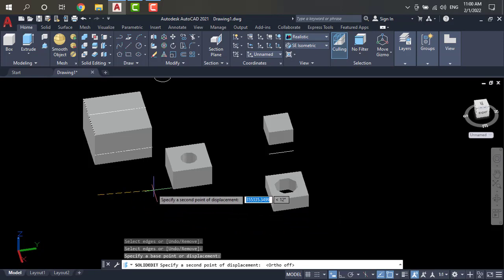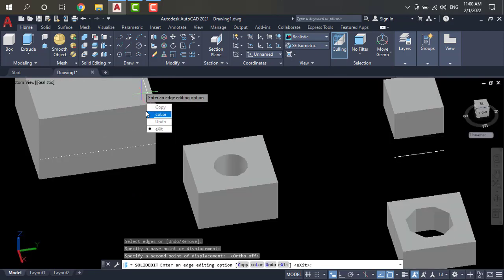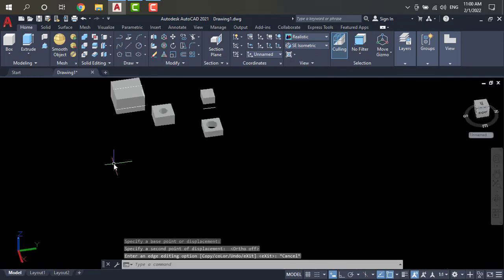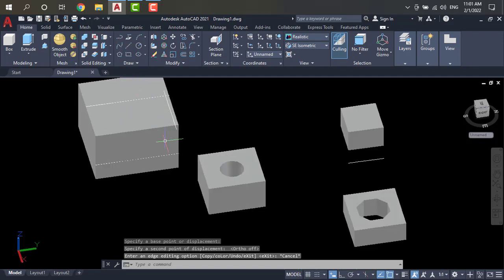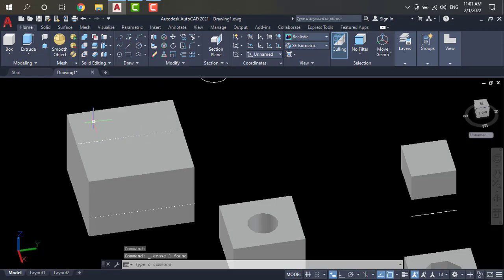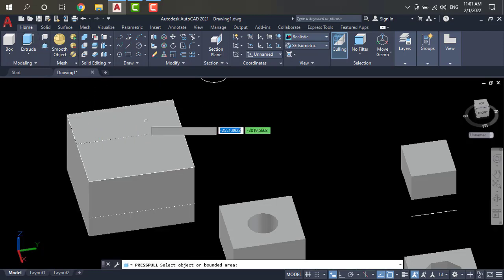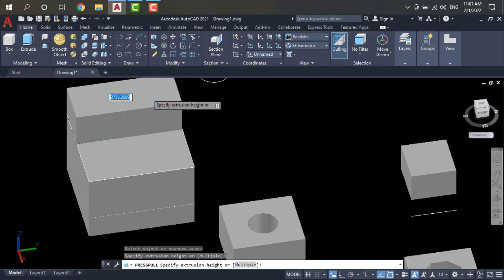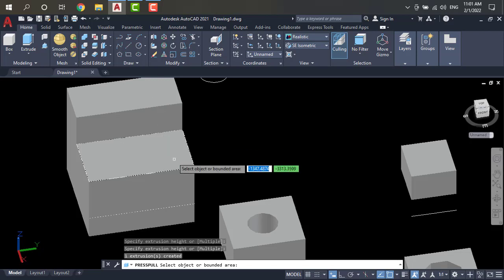So I am taking here our edge, and our edge is not copied exactly. Here it will be outside. When we copy the edge, it should be copied exactly. Just select this line and delete. Why? Because I want to extrude or press pull this. It is more useful for us. The edges are perfectly attached to the boundary lines.